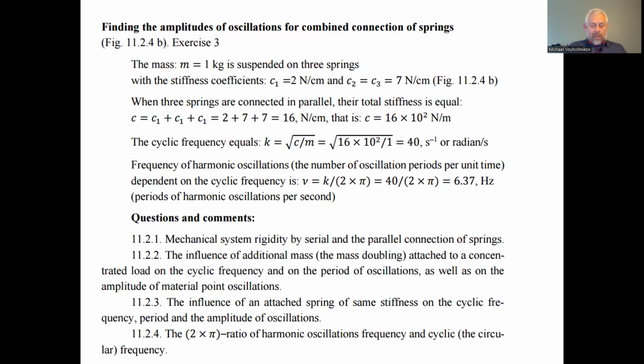The period of the oscillation accordingly increases, and the amplitude of the oscillations increases in the same proportion, as the square root of the proportion of the stiffnesses of the suspension of the springs in series, compared with just one spring of bigger stiffness and lesser softness than the springs in series.